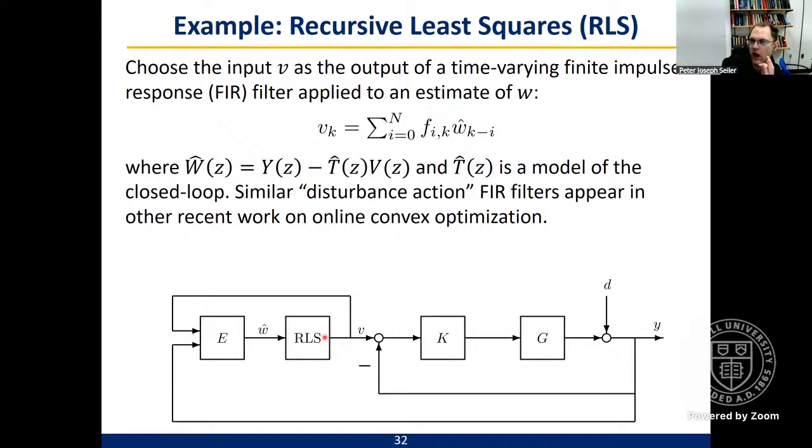the number of coefficients, is telling you how far back in time you are using your estimate of the disturbance. If you knew what the harmonic frequencies were in the disturbance and you knew the sample time, you could try to pick n so that you've gone back one or two cycles of the disturbance. As you pick n bigger and bigger, obviously at some point you're hitting computational or memory limits. But at least that gives you a way of saying, I'd like to predict what this extra input should be based on a couple cycles of what I think the disturbance might be doing.